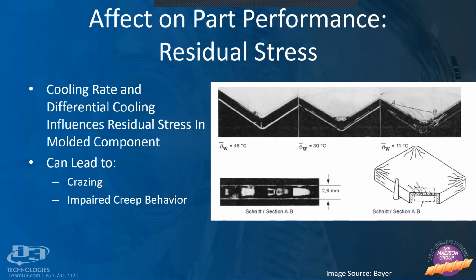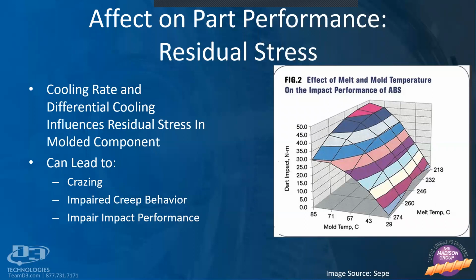The other thing is that the reason we got that cracking was because of the residual stress, and our plastic is going to want to relieve any residual stresses in our part. So if we don't cool this part properly, we could get crazing over time, or again, impaired creep behavior, that long-term behavior for our part. And then on the short term, again, with some materials, if we don't pay attention to the residual stresses, we can see a diminishment in the impact performance of our part.